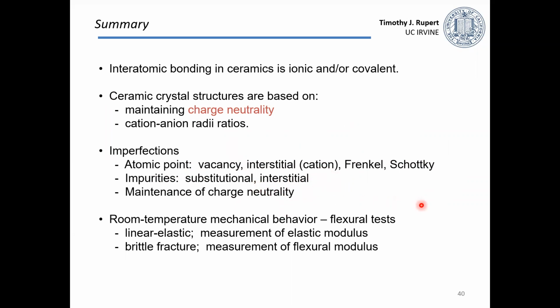And finally, for mechanical behavior, if we're doing this at room temperature, we tend to do it with these bending or flexural tests. We get linear elastic response that we can use to measure that elastic modulus. And then that fracture strength can be used to figure out what the strength of our material is.